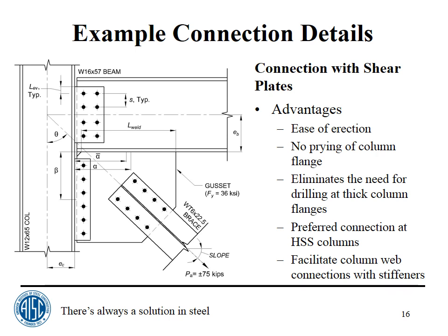If it's going to column flanges, you can just slip it in sideways and get a drift pin on each end, and then maybe a bolt in each hole, or a couple of bolts at each end. Then the erection crew moves on, and the bolt-up crew comes by and puts all the rest of the bolts in. Really works slick. It works just the same way for beam to column without the bracing connections.